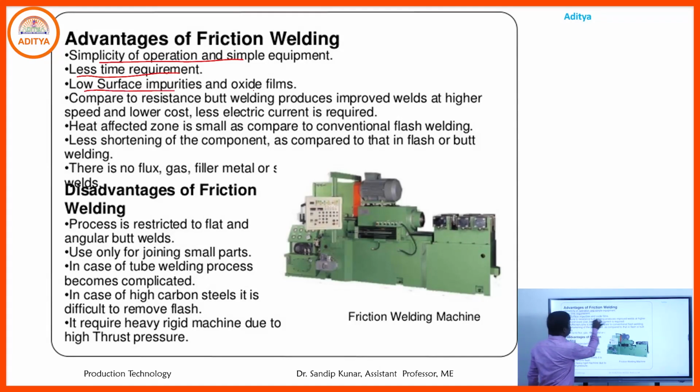Another advantage is low surface impurity, meaning the impurities or contaminants are very few, and there are fewer oxide films. Generally, a very small amount of material is melted, which is why very few oxide films are generated in the weld zone.